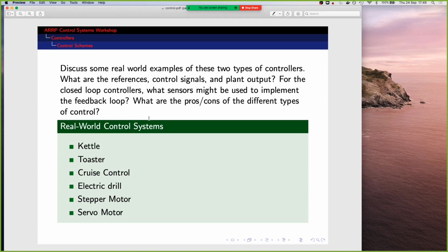Yeah, exactly. So there's a few things that go into implementing cruise control, but I think most importantly, the feedback is the wheel speed. I don't think they measure true ground speed. So for example, if the wheels were spinning, you'd get a false reading on your cruise control speed.